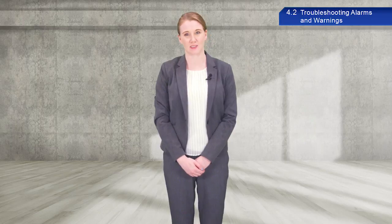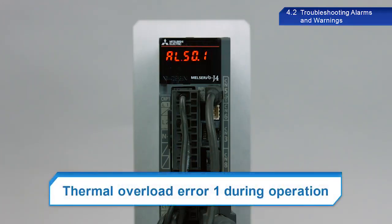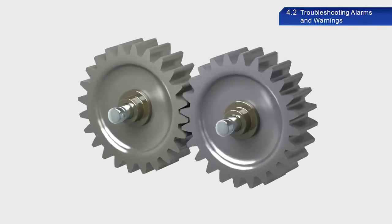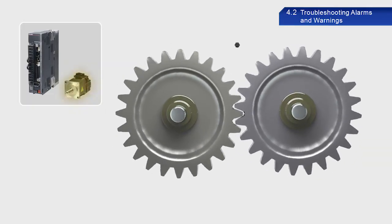Besides noise, harmonics and leakage current can also negatively affect servo systems. Alarm code 50.1 is the thermal overload error 1 during operation alarm. This alarm occurs when cables are disconnected or scrap material is jamming equipment. Objects can jam moving parts of equipment, causing them not to move correctly.